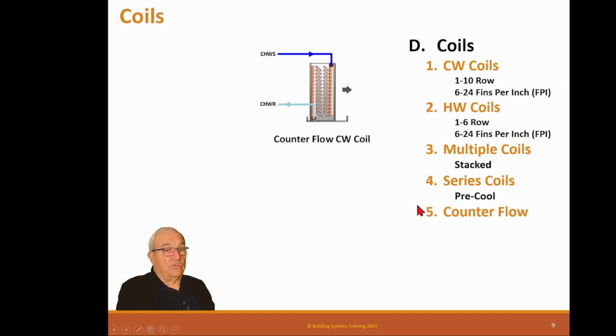So counterflow is really, really important on chill water coils. On hot water coils, it's not as important, but actually the same principle applies. We just don't need it for water removal. So what I always taught my installation technicians is just always pipe all water coils with the supply water on the downstream leaving side. Then you'll never be wrong.